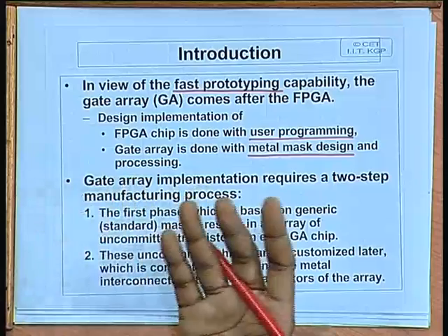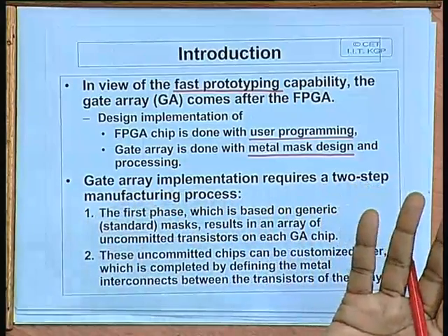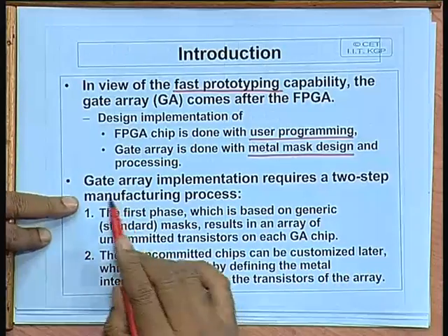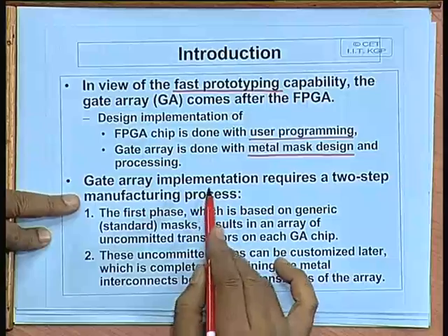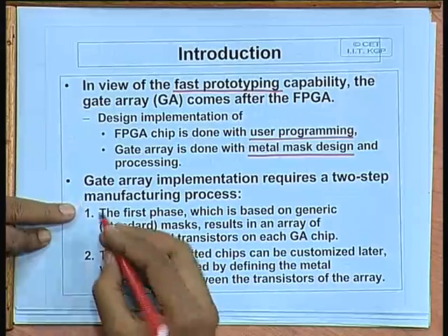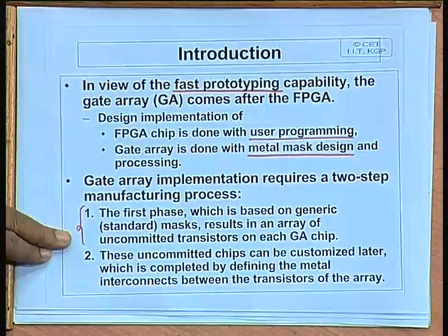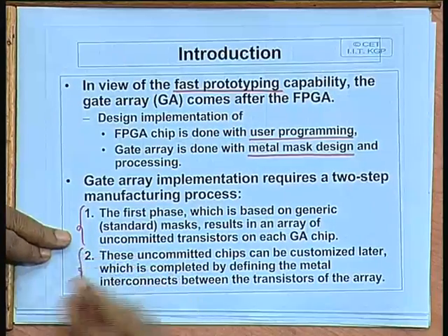But in that case, what is the difference between a standard ASIC design and gate array design? There are differences. The cost becomes less. Gate array implementation requires two steps of manufacturing. The first step is independent of your design. The second step is specific to your design.